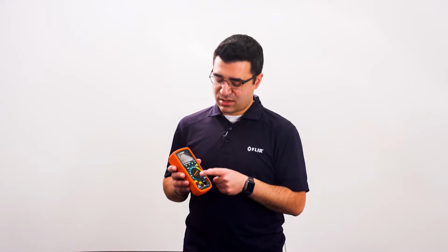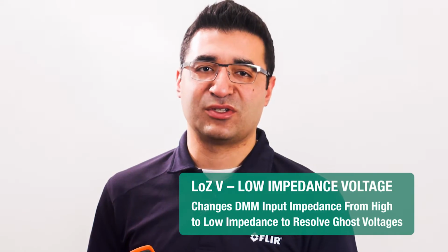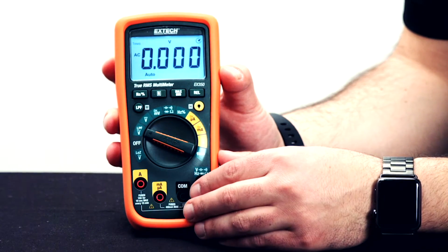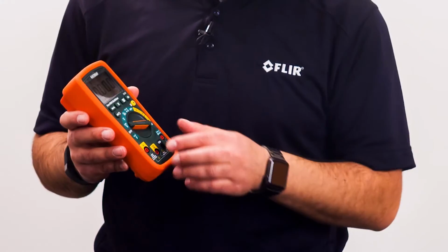To start, Low-Z V. This is the low impedance voltage function. This changes the DMM input impedance from high to low to resolve ghost voltages. Next, low pass filter voltage, LPFV. This setting applies a low pass filter to AC voltage measurements for proper measurements of VFD drives.